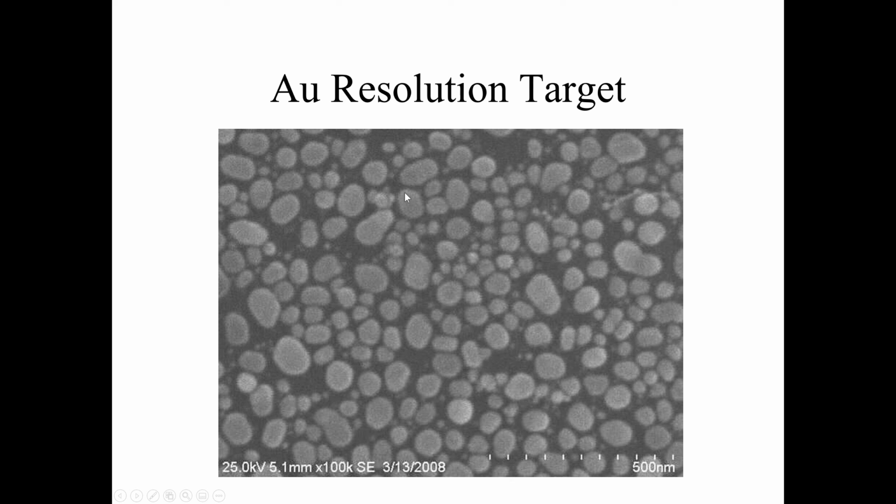That's one of the assumptions people make when they run to the lab: well, I heard your microscope will do 5 nanometers, I want to see my image multiplied at 100,000 times. Each material has its limits on how high you can magnify. Hitachi professionally prepares a gold target. It looks like a little gold coating on a stub, but under the microscope you can see the growth plateaus of these deposited gold atoms.